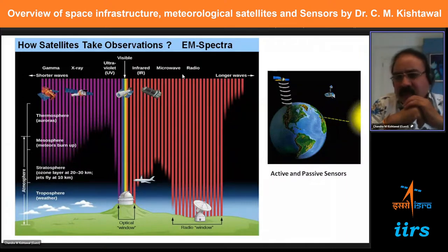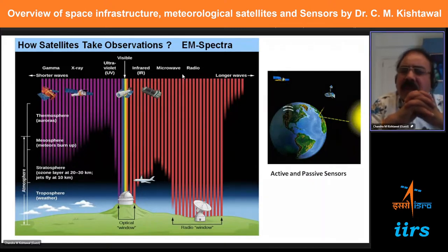So for those purposes, several instruments use active sensing. Active sensing gives a lot of other advantages. For example, you can pinpoint a particular frequency for a particular purpose, and you can determine the resolution of your sensing also, depending upon the amount of light. A lot of other special kinds of instruments can be built upon that, like the synthetic aperture radar. Making a synthetic aperture radar from passive sensing is slightly difficult and not so successful. People have tried to make a synthetic aperture radiometer also, but it was not so successful. The signal to noise ratio was quite poor.